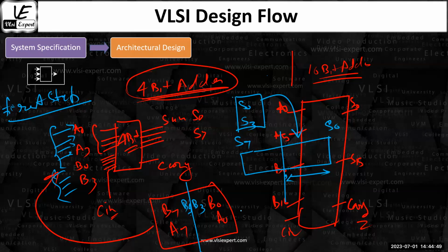So I'm just considering this as a single cycle. In the first cycle, from a clock point of view, in one cycle, you are going to do the 4-bit addition. You are going to save that particular output in an output register and done. Then in the second cycle, you will give this set of data here again, and then you will get the output here. So that means in 2 cycles, now you are able to do the addition.